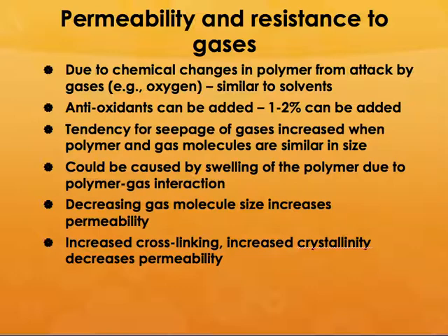So you would put it into a system where you have a gas on one side and you measure the amount of gas that is leaking through the composite over a period of time under different conditions. It could be under cryogenic conditions, it could be under heat or moisture and things like that.